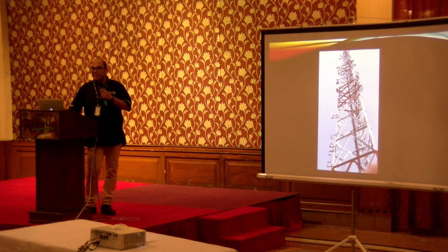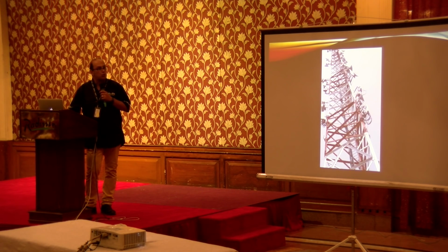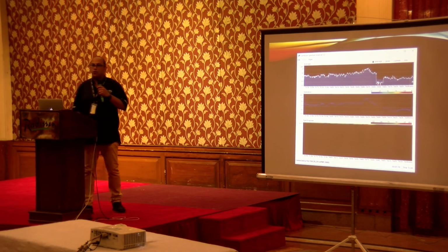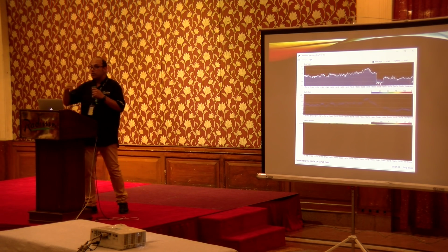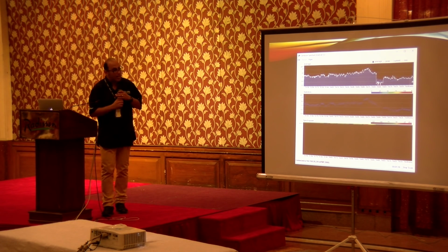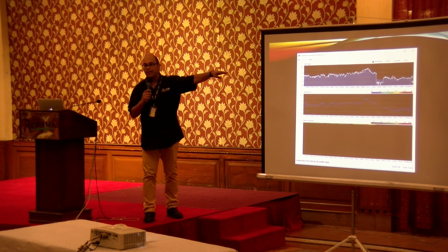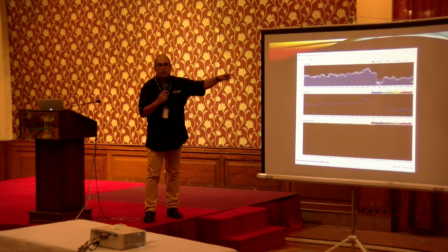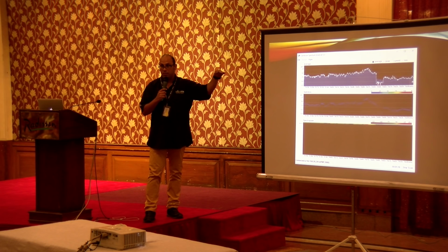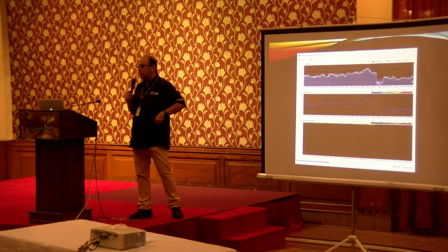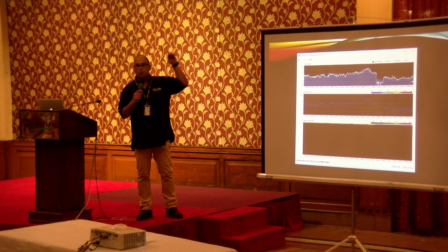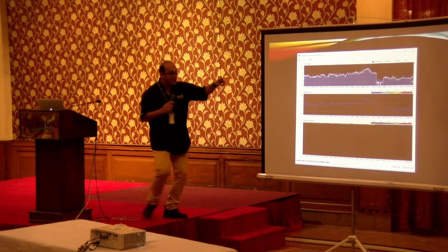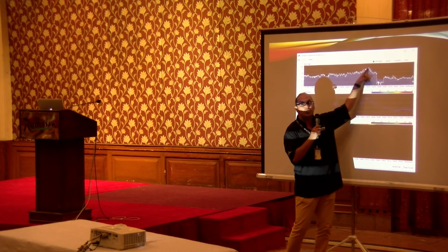For this type of tower, it's really interesting to show you the spectrum analyzer. We were analyzing for a week to find a free channel. Not a free channel, but the least noise, least interference. As you can see, this is noise. The average of noise is something like minus 60. Minus 60 is the average of the signal you need. This is very high power. This is the highest noisy environment I have ever seen. As you can see, in some places it reaches even minus 25.